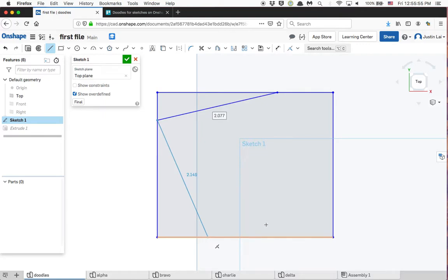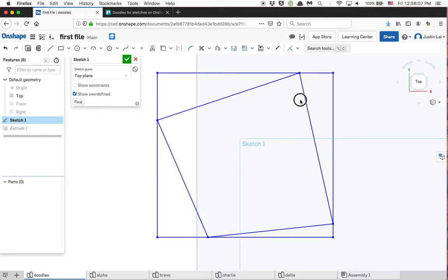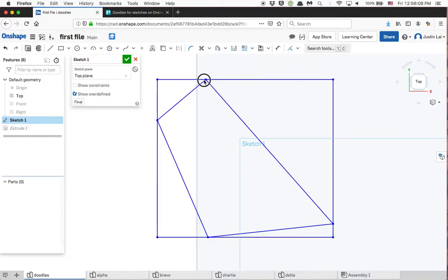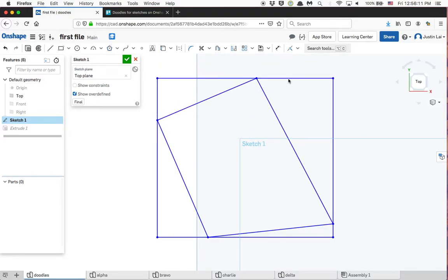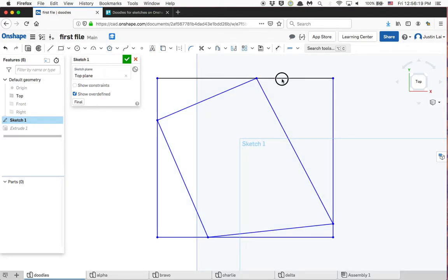The only inference, the only help, is just making it coincident. And let's connect it. Okay, boom. All right, drop the tool. And then now take a look at how you can actually move both the rectangle and the inscribed shape. Let's say we didn't want the top piece to move around, so we could pick that top one, and just for ease, we can just fix it, right? It means it's not going to go anywhere.